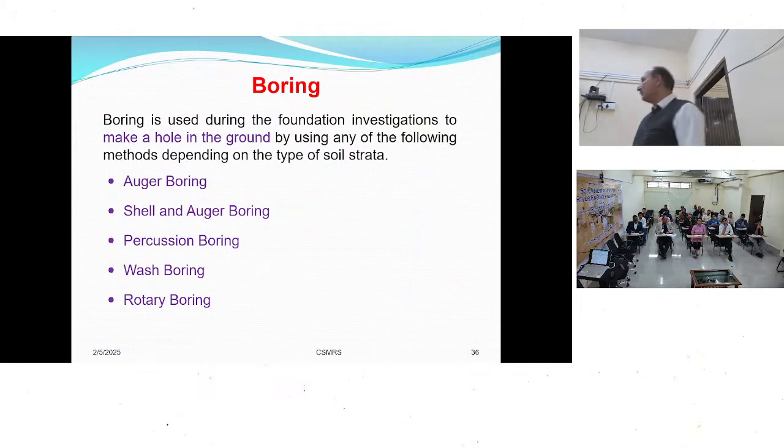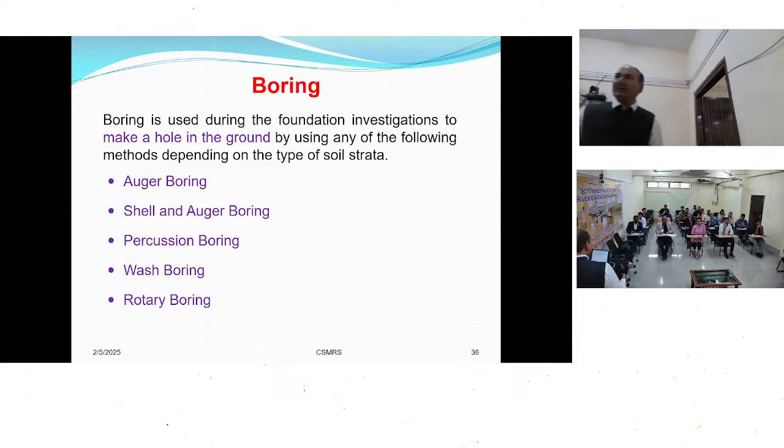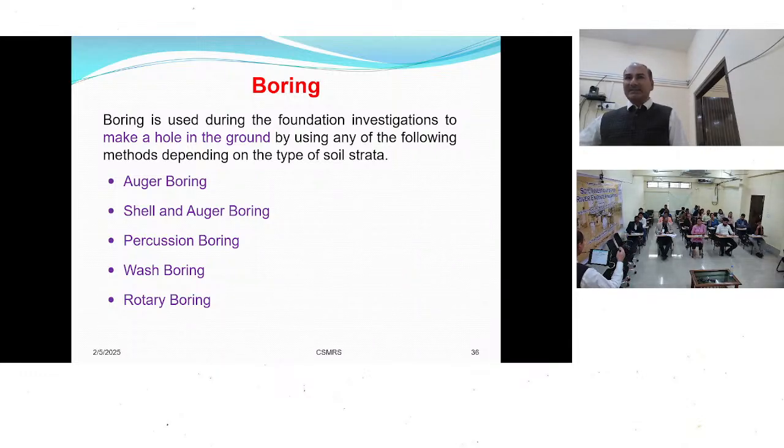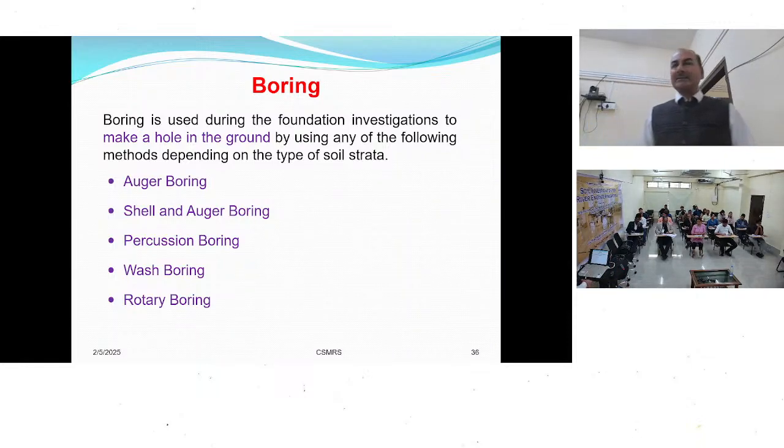So what is boring? Boring means drilling a hole into the ground. That is called boring. Drill holes, bore holes. I think everybody has heard that. After drilling the bore holes, what do you do? You collect the samples. You carry out some tests in the bore holes, like the in situ permeability test.